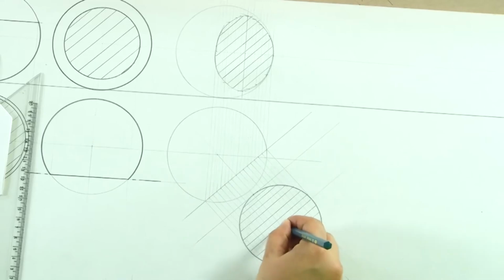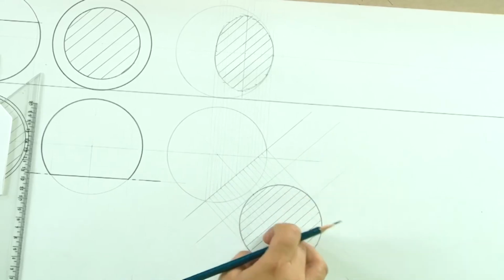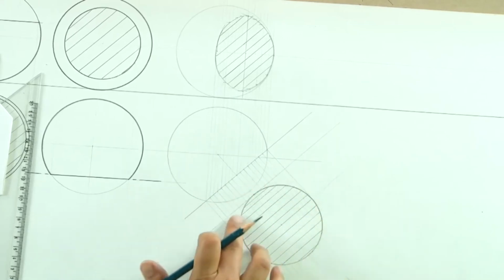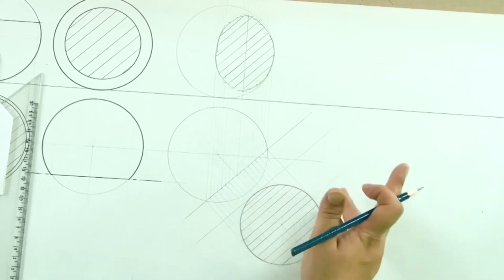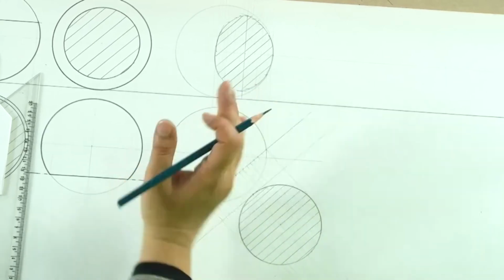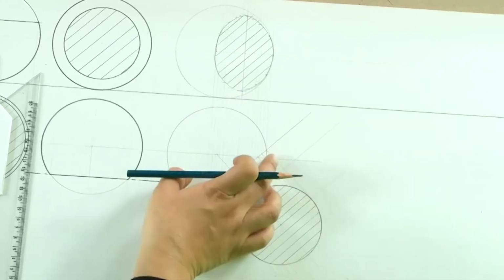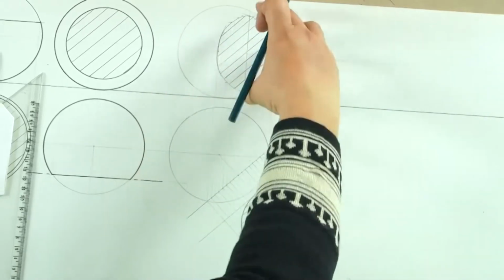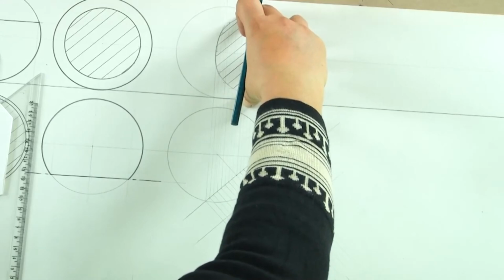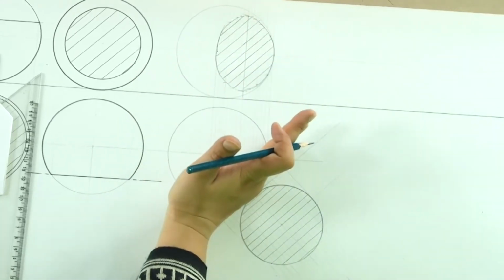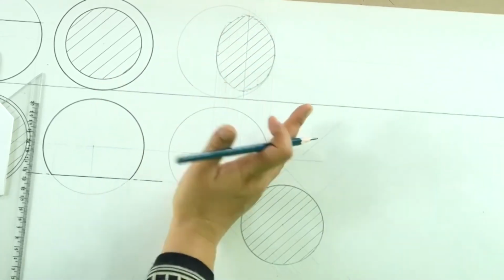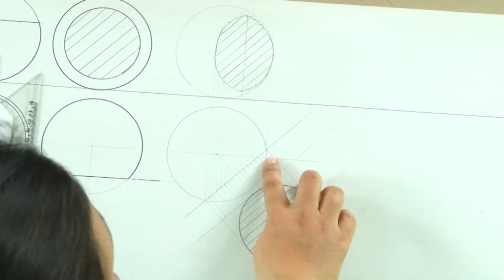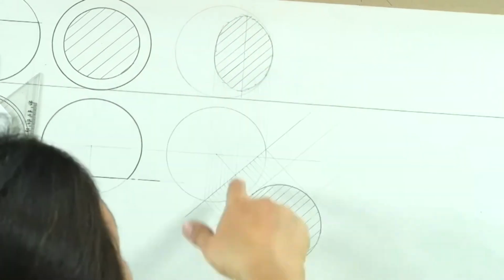So if this is the diameter, we can just make a circle, and the relative position of all these points which we have taken as parallel circles on the sphere, and then since it is inclined, what you see in the elevation is slightly skewed. So this dimension has reduced while this dimension remains the same, simply because this plane is perpendicular to HP, it is inclined to VP.